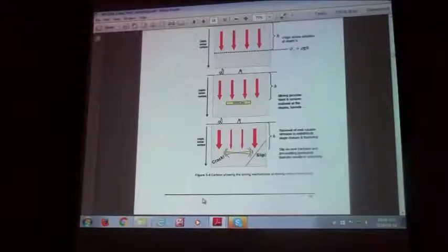Now, when you start working in mining seismology, you start to use a lot of engineering properties. And one thing you need to know is the strength of your rock. That becomes a very important parameter, because that's what provides the support. So how many of you have worked in a rock mechanics laboratory where you've done tests of rock strength?